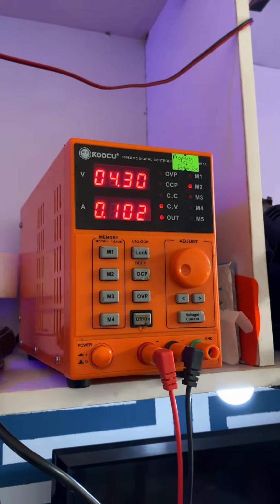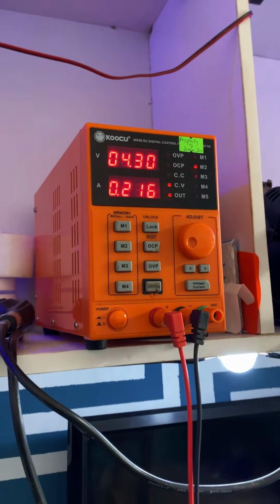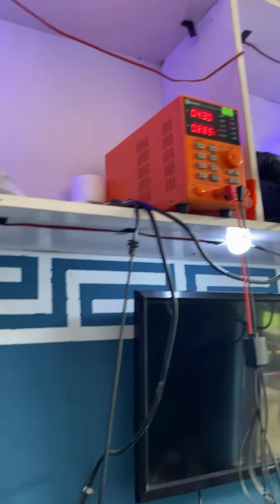Okay, so here is the power consumption. So you can see the power consumption. From the power consumption, you can see that nothing is wrong with the power IC. The power IC is doing its work perfectly. There is a particular resistor on the phone PCB that is not supplying amps to the power IC.